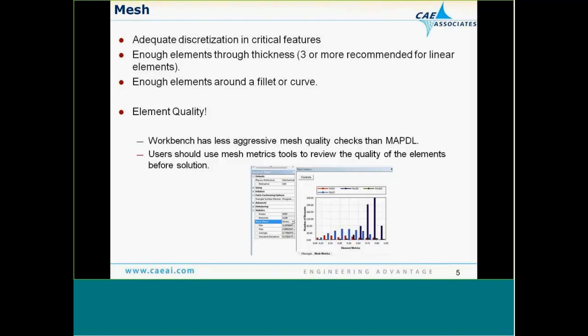If you used ANSYS MAPDL, you'll find that you get many elements that generate warnings and possibly elements that generate errors. Well, Workbench either creates a mesh, which means there were no mesh errors, or it doesn't create a mesh, which means the elements failed their quality checks.